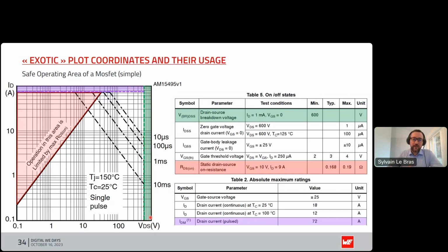And now we're going to see how we can stay within the limit and check if we are within the safe limits. So the safe limit is a fraction of the white region. And depending on the time you're spending in these regions, you can go further and further. But if you are planning to stay, for example, longer than 10 microseconds, do not get in this region of a combination of voltage and current in your MOSFET, or else you will destroy it. It's the same if you're not starting from an original temperature of 25 degrees, do not get as far in these regions.